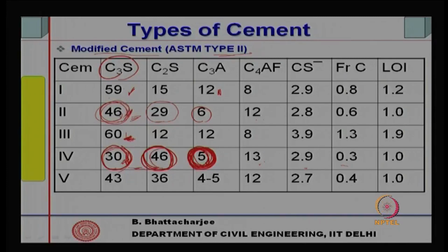We will look into the strength development sometime later on. This one has a very high early strength, but later strength is not good. Even that can have problems related to durability, etc. But at the moment, this was the purpose of rapid hardening cement, its usage is where you want early strength.